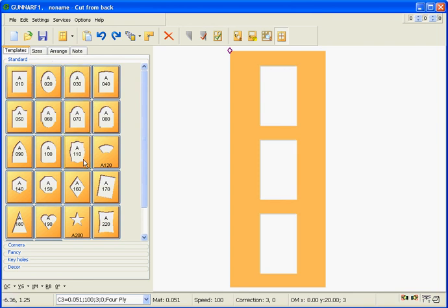Underneath the toolbar on the left-hand side, we have our Edit area. This is where you choose your template and edit the layout. To the right of the Edit area is our Work area, where the current layout is shown. Underneath the Edit area is the Options bar. Here you can add options like outside cut and V-grooves to your layout. You can learn more about these later on.